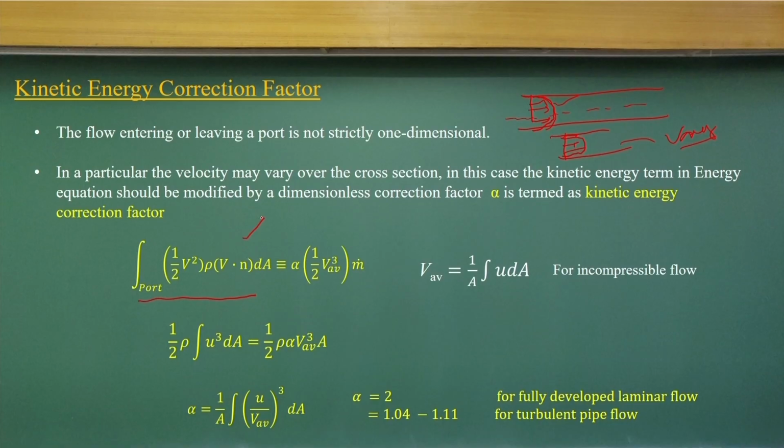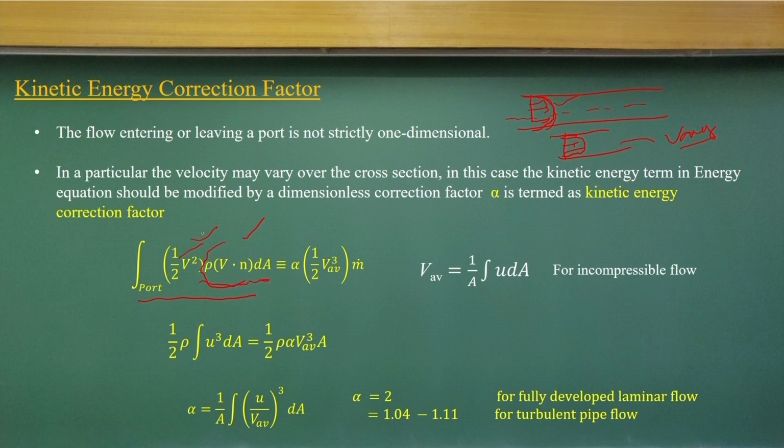So when you apply the kinetic energy, we look at the total kinetic energy, which we can integrate over a small dA element. Here rho v dot n is the mass flux, and half rho v squared is the mass flux times v squared by 2, the kinetic energy flux. We do the integration over the total area dA, and we have the kinetic energy.